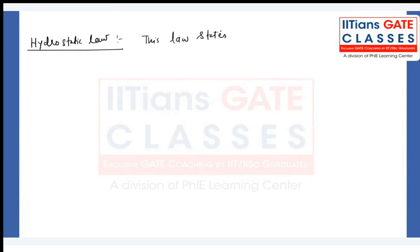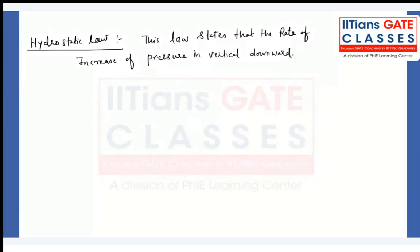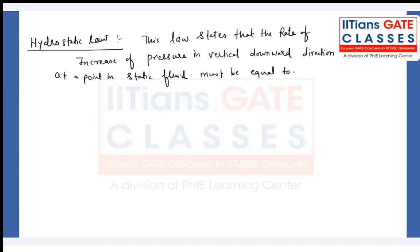This law states that the rate of increase of pressure in a vertical downward direction at a point in a static fluid must be equal to the local specific weight of the fluid.